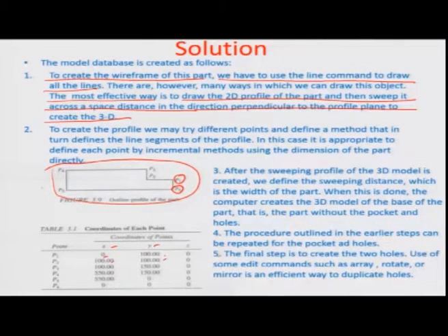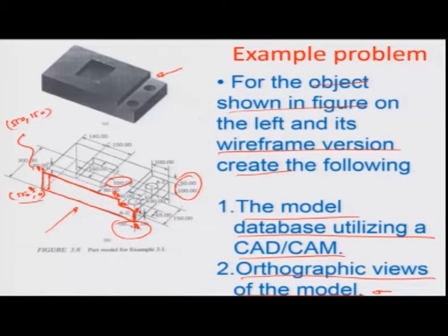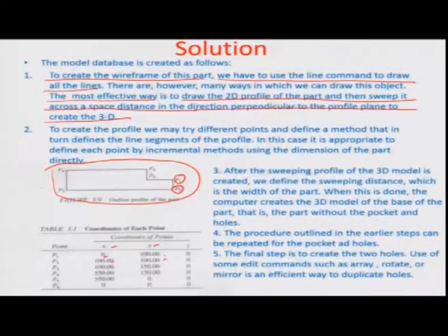You can actually go back to the figure and compute this yourself looking at the different dimensions, and then you basically create steps of z from 0, which is this right here, all the way to about 300, which is somewhere towards this corner. So, this is the first step of creating the whole solid block without any of these different cylinders or cuboids extracted or cut out of the particular geometry. So, that is the first step towards creating the wireframe of the solid model.